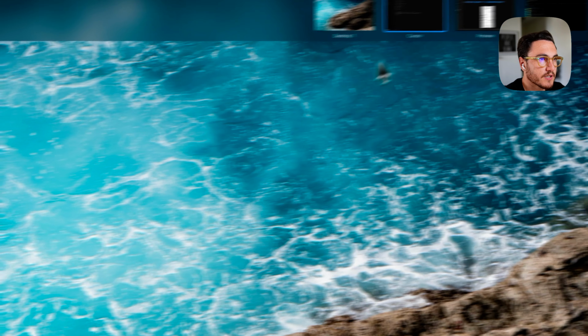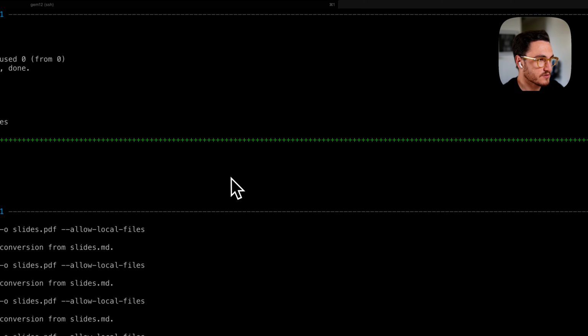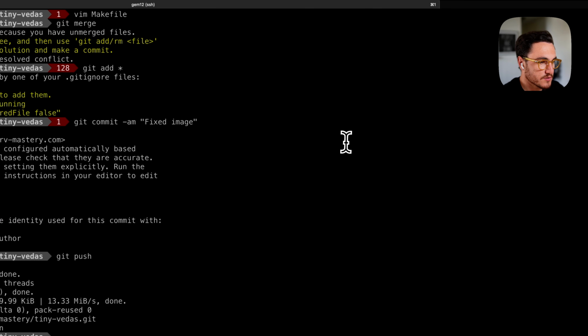So if we want to run a co-simulation, so if we want to run RTL and the instruction set simulator together, what we can do is use this command where we specify the name of the test and the simulator, which in this case is called Verilator. So this was extremely fast because I had already everything compiled.